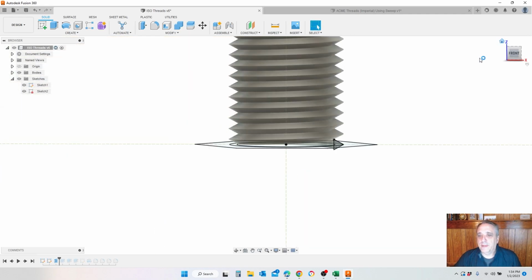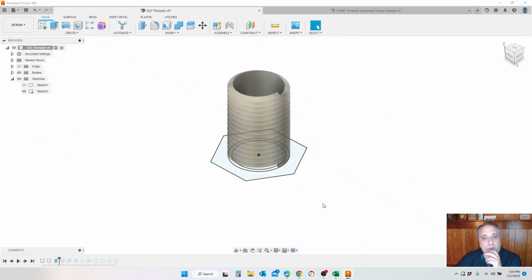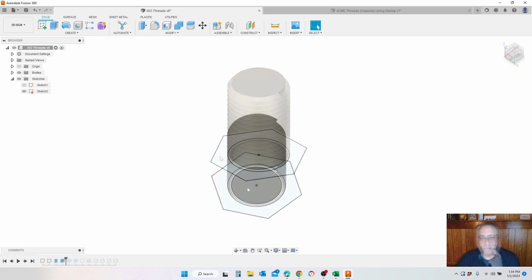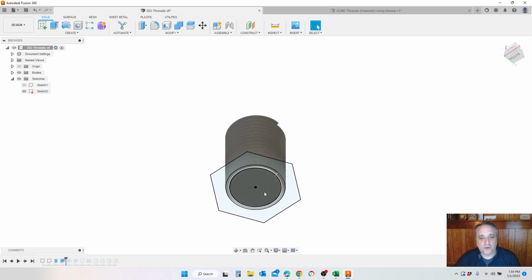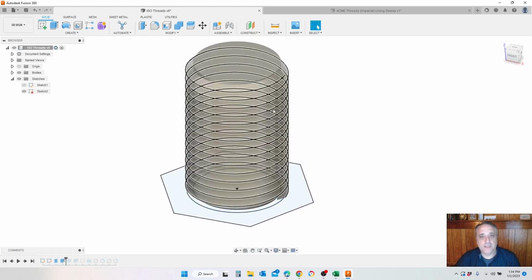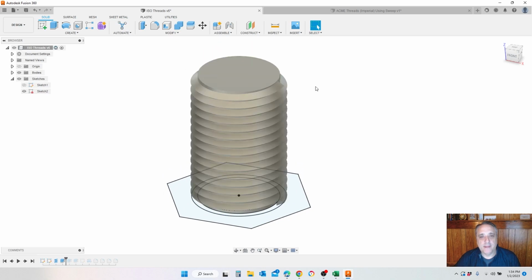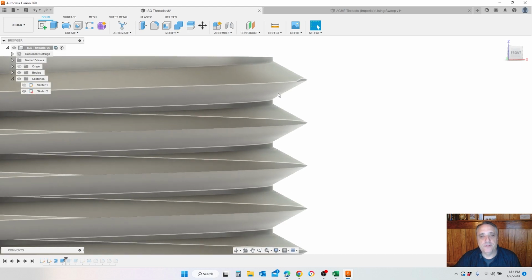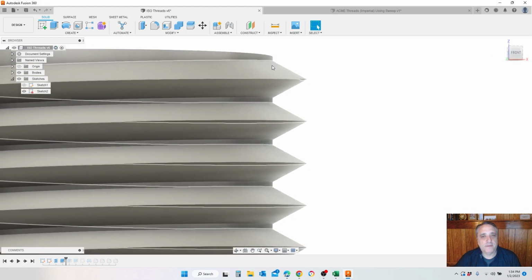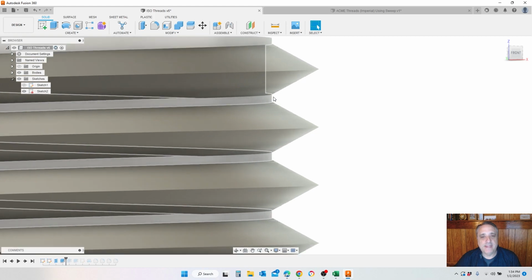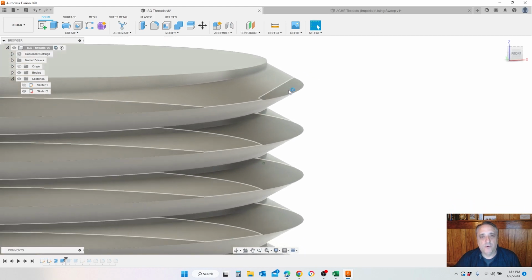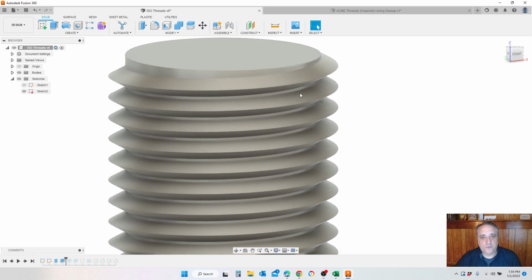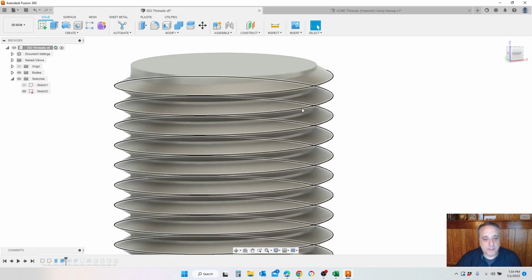All right, so we have our coil. The next thing we're going to do is make this into more of a solid part. The first thing I do is that interior circle profile, we extrude and create a new body, and it pretty much just creates that body. And you can see by the size that we picked, it flattens that inside trough for us. So we picked the dimensions right and put in the right equations.